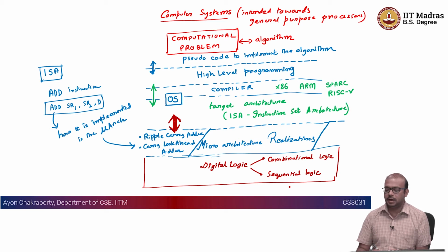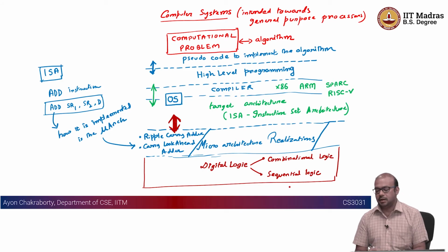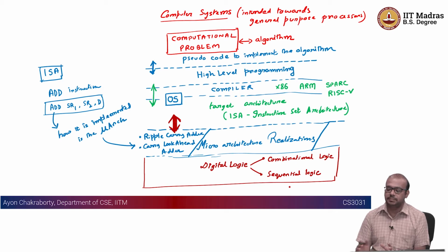It does not take n number of clock cycles to do this. They can take multiple gate delays, right? But gate delays are much smaller, right? Could be a few nanoseconds or like 10 nanoseconds, right? And you may have a critical path where you might be having to cross 3 or 4 gates in the worst case, right? So that is basically your propagation delay, or the delay for your combinational logic.